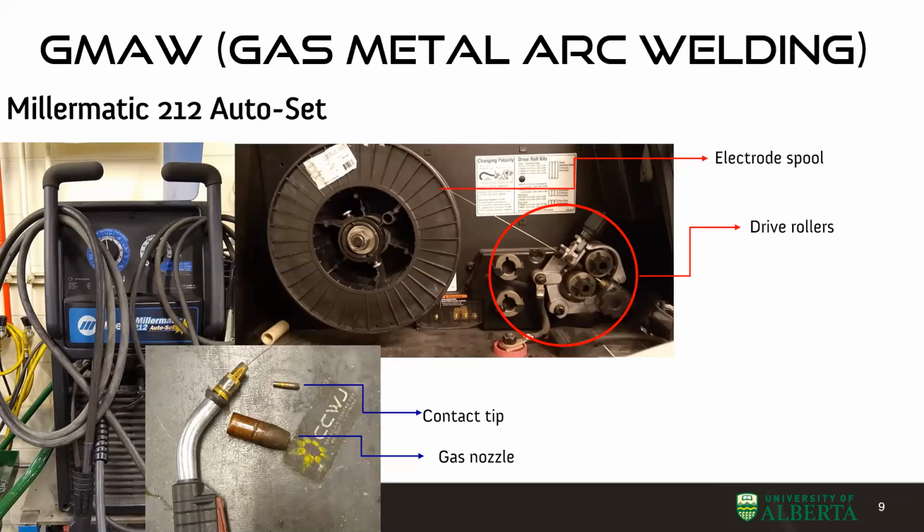One quick thing here. Starting in all these semi-automatic processes is very, very difficult, and much of the algorithms inside the Lincoln and Miller machines are about the start and the stop. What Wesley was saying is true. These electrodes, especially in submerged arc welding, have an amount of silicon and manganese to deal with oxygen. When you stop the arc, that silicon reacts with the oxygen in the air and creates silicates. And the silicate is just ceramic, silica, like a layer of glass.